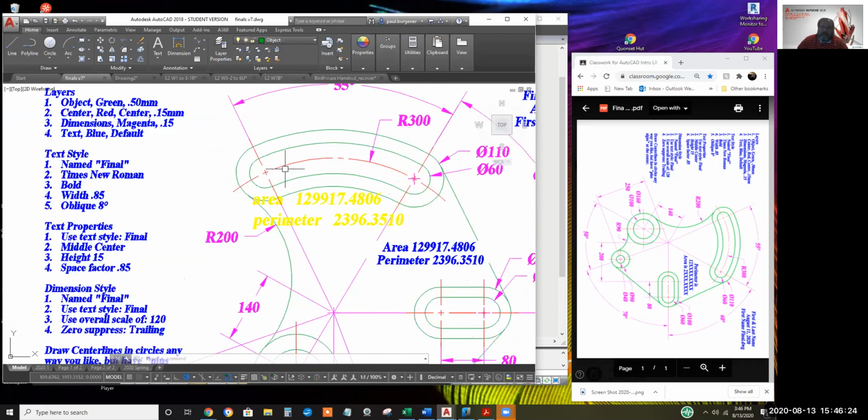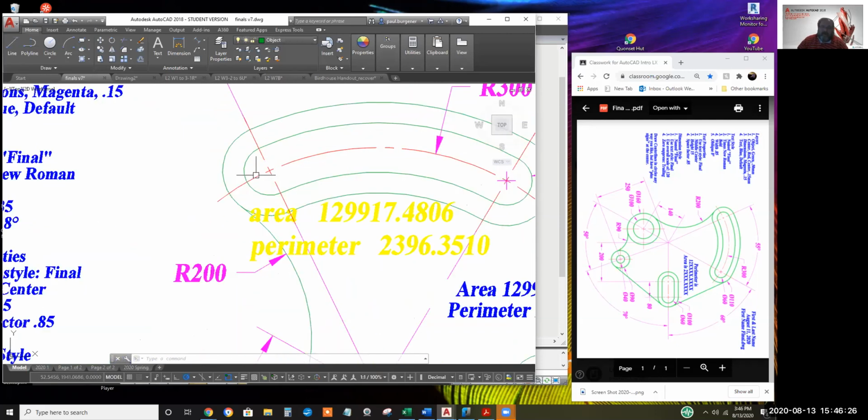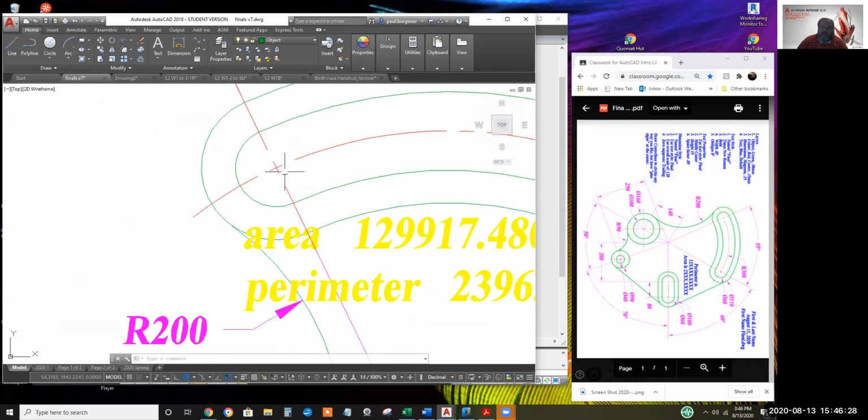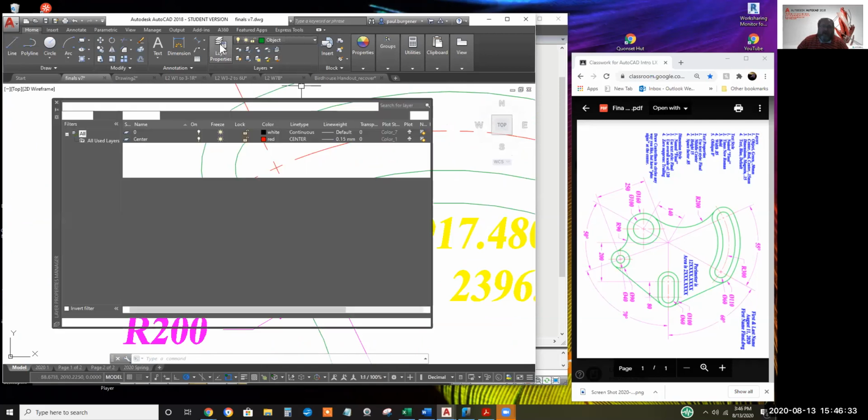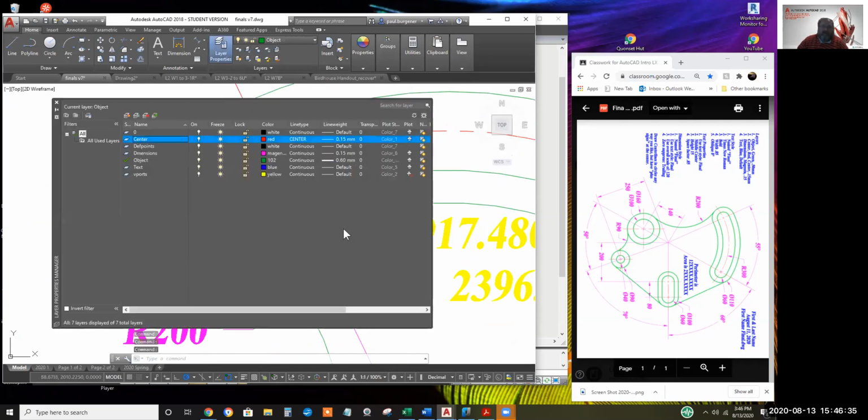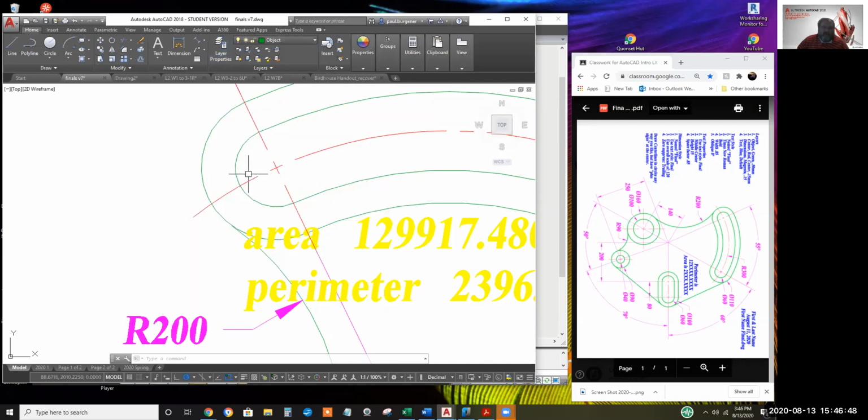And I'm going to be lenient on the little plus signs here. I used only one red layer of center line. And each and every line or arc drawn on the layer named center is assigned a specific line type scale multiplier factor in its properties.